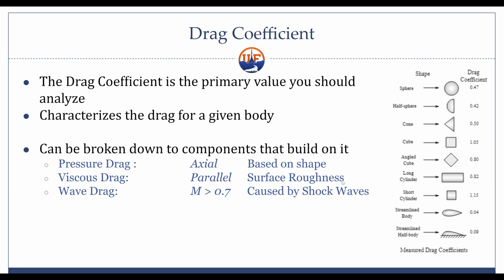Because what's going on is essentially at the front of your body, there's no shock wave. At least, I'm talking about the nose cone tip, there's not really any shock wave because you're still going at 0.8. And as it travels through that body, and your body squeezes the air, think of going through a pipe, and the pipe is squeezing it, or like your thumb going there. That's a compressibility effect. That's accelerating the air past the nose cone, and that's what's going to produce your shock wave.